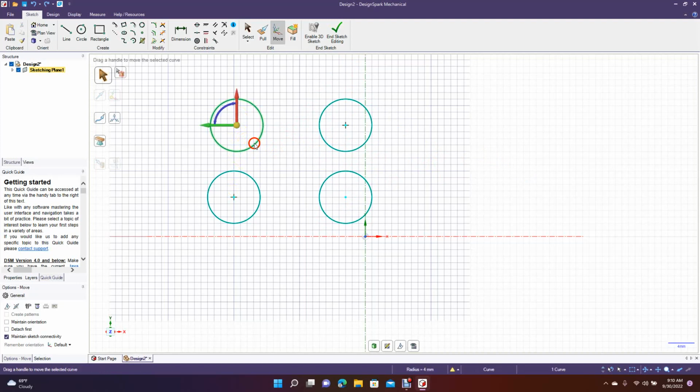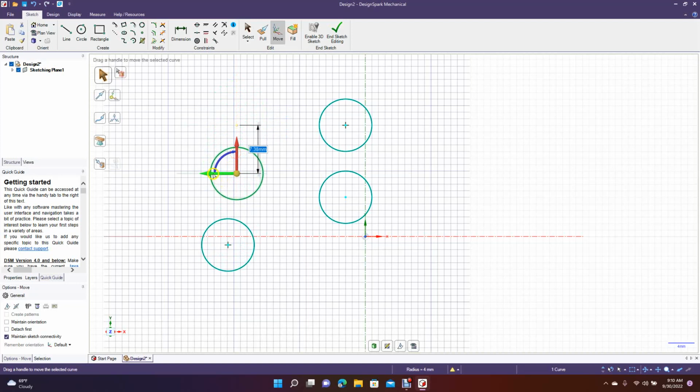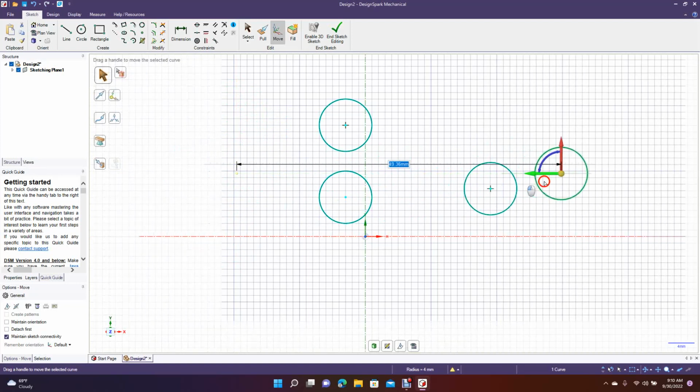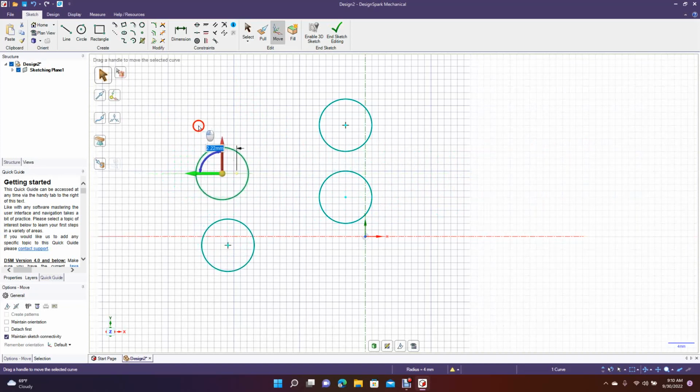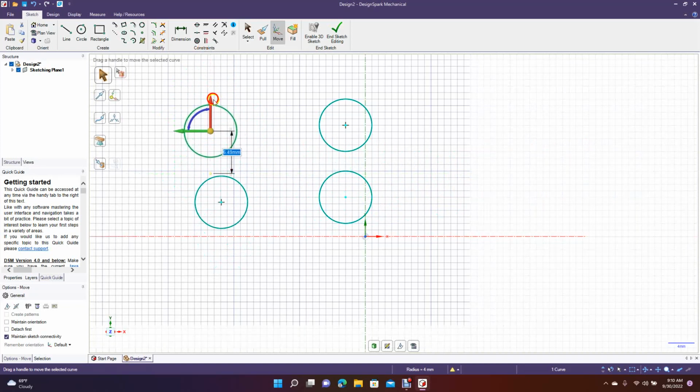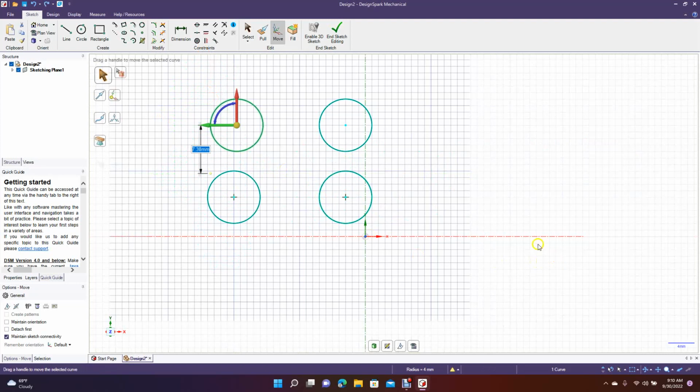So this is going to be that way regardless of what you do. Move it over here. It's keeping the same space. Undo that. Okay, so that's going to be your equal distance constraint. You're telling it you want certain space, whether I move them or not.